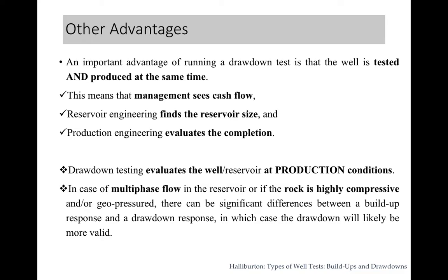Drawdown testing evaluates the well and reservoir at production condition. We already discussed this in our previous slide. In case of multi-phase flow, this is very important. If the rock is highly compressible, there can be significant differences between a build-up response and a drawdown response. So it is the multi-phase flow which is causing difficulties in the two different types of test.